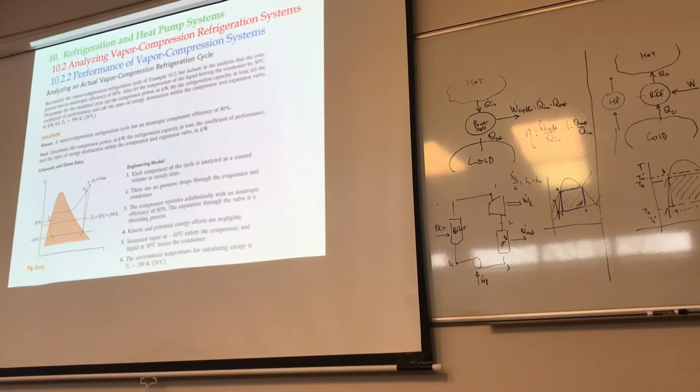And this one is the one that I wanted to look at, repeating that same example but now with an efficiency. This problem involves the fact that this temperature is -10, this is 30, but now we are not efficient here either. In other words, the compressor has an efficiency that is not 100%. What do you expect that beta to do?